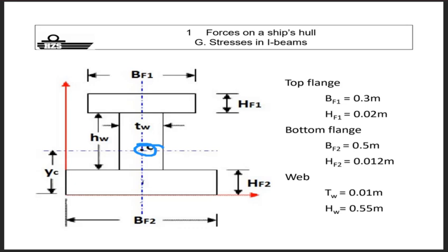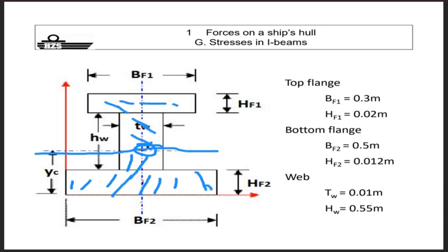It's not necessarily the middle, because it's not symmetrical. Your area center of gravity depends on how the material is distributed. You see here, if you go into your reference line of your neutral axis, the amount of area below is exactly the same as the amount of area above, but it's not necessarily mid-height of your profile. If your profile is 100% symmetrical, then of course it will be exactly in the middle, mid-height.